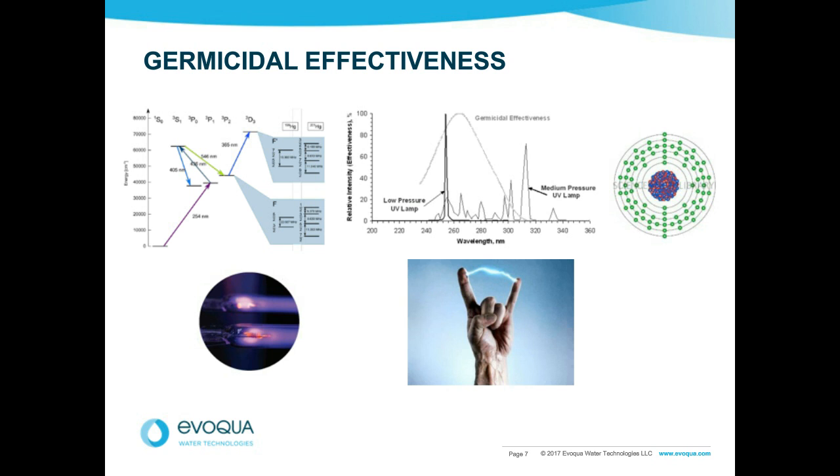Amine, okay, yeah. Look, we do a lot of monochloramine and trichloramine destruction. We look at the way that these molecules absorb UV. We look at what wavelengths they can be broken down by. We study the molecule. We look at what chemical bonds they have, and then we look where these bonds will resonate, like we showed in all the examples of resonance. So we look at how the bonds absorb the UV. We will then size a system to remove it.